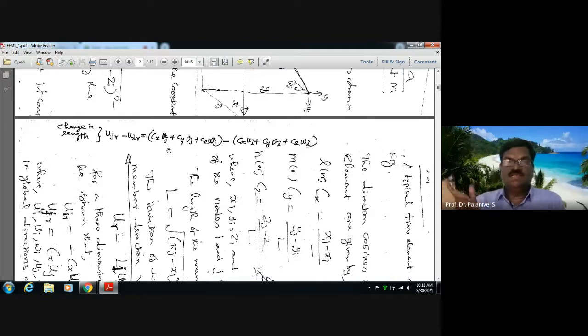Okay, cx will give me its resolution along the r direction. I am resolving the displacement in the r direction. Similarly, I am resolving the displacement in the y direction along the r direction. That is cy vj plus cz wj. The sum will give me the final displacement of the jth node in its own direction, the r direction.